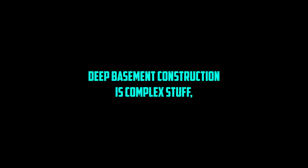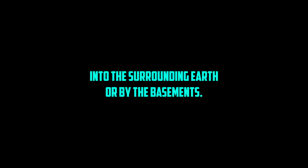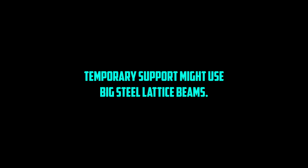Well, a basement is just a story below ground level. Deep basement construction is complex stuff, often done within a temporary cofferdam or supported excavation. Techniques like diaphragm walls can be used, supported permanently by ground anchors drilled into the surrounding earth, or by the basement's own floor slabs acting as props. Temporary support might use big steel lattice beams.